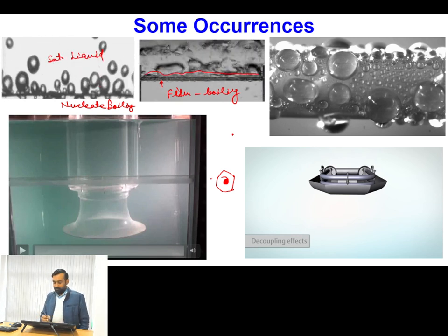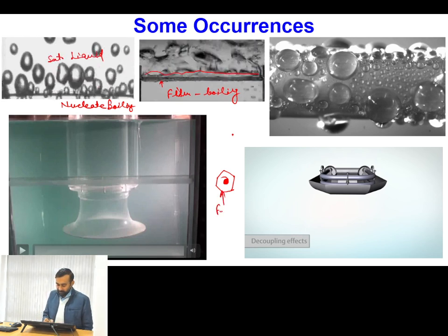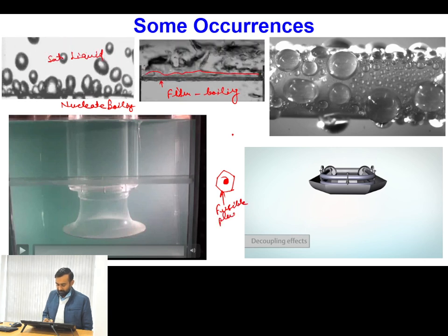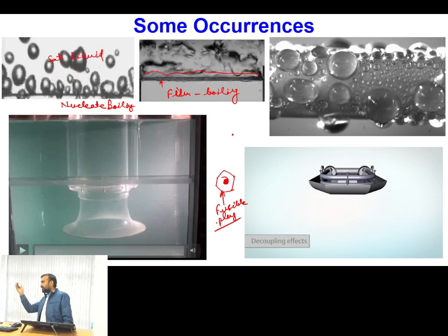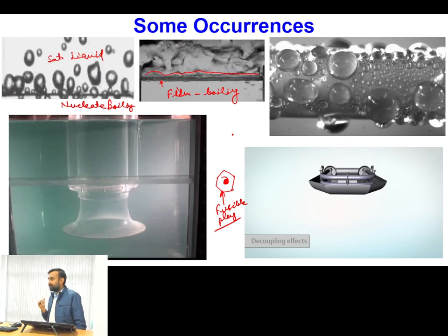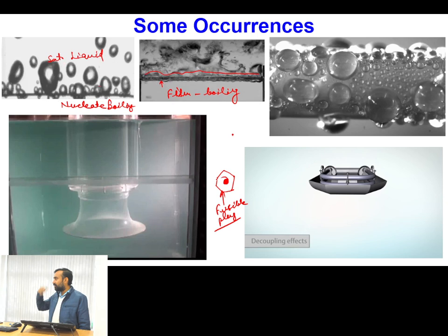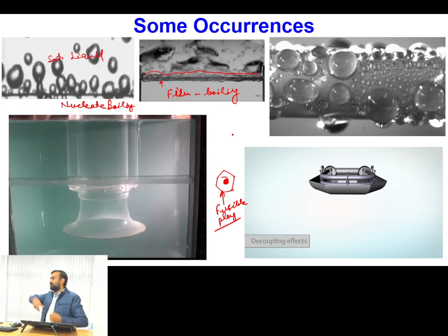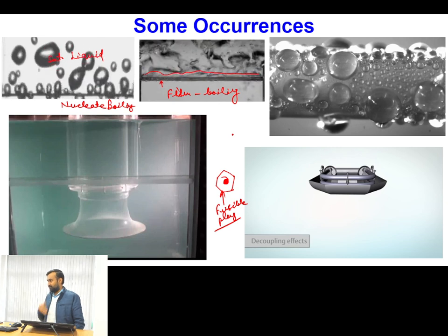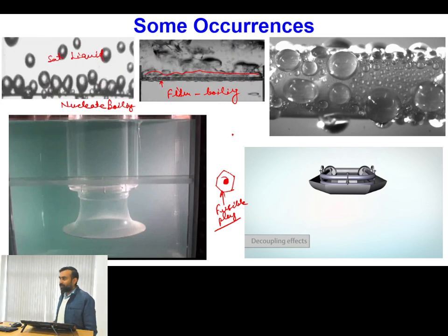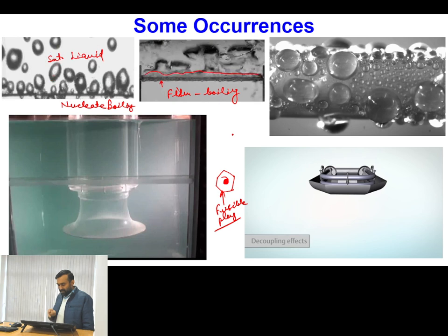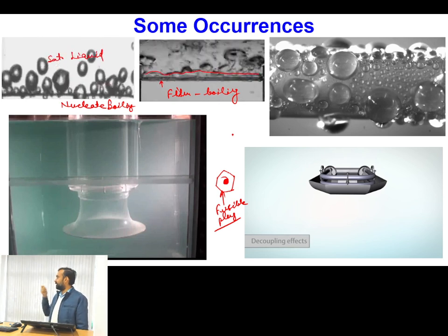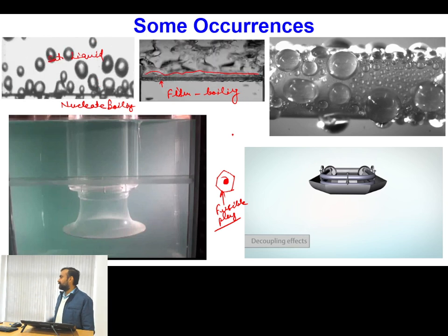Okay, what is this? This is a fusible plug. Once the temperature and pressure get excessive within the cooker, if your whistle is not lifting, then ultimately it breaks and the entire steam comes immediately out. So even after regular use of the cooker for a few years, sometimes we need to replace this. Okay, in certain scenarios, after its long use, it actually gets melted.